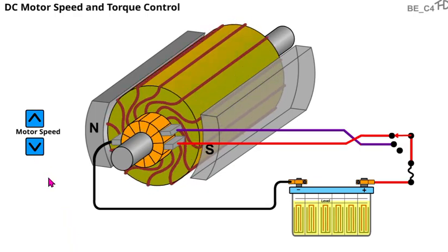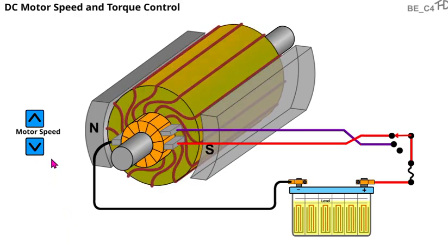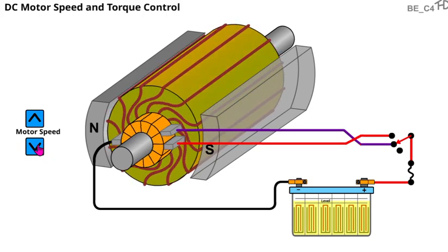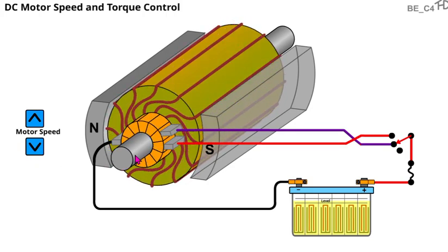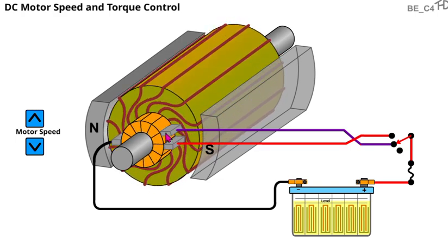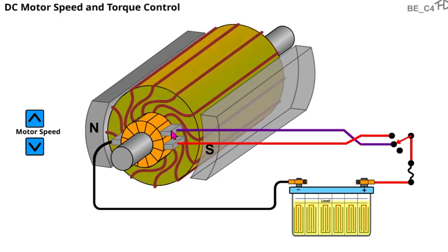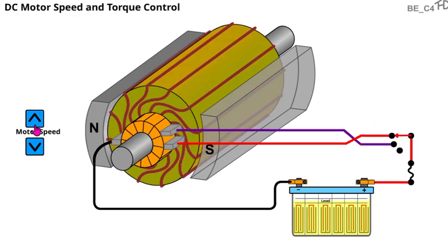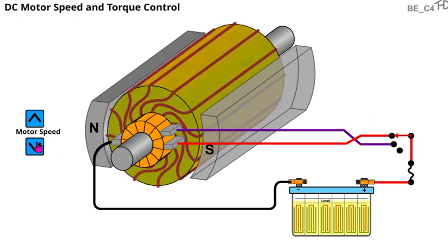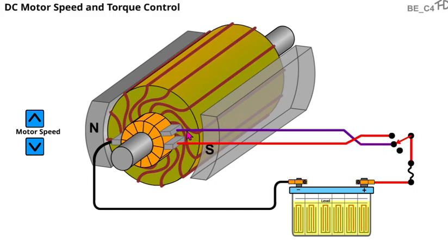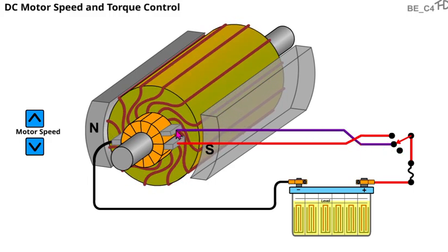So here's an alternate version where we have an offset brush or a third brush, which will give us a 2-speed motor. By offsetting the brush, we decrease the amount of time that there is power being conducted through the coils, which slows things down. So you can see a little switch occurring here, high speed, low speed. Our low speed is our offset or purple wire here, our offset brush,